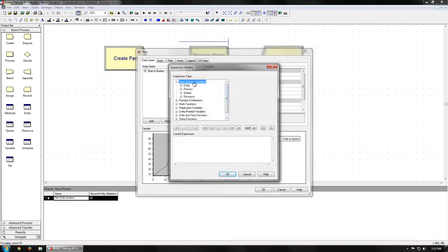And right here you've got basic process variables. Let's go to Q, and we want to do current number in Q. So click that, and you'll notice that the expression changes down here to in Q, and then it's got in parentheses the queue we're interested in. You can change the queue here or manually type it. We've only got one queue, which is this one, and that's the one that put it in there. So that's exactly what we want.